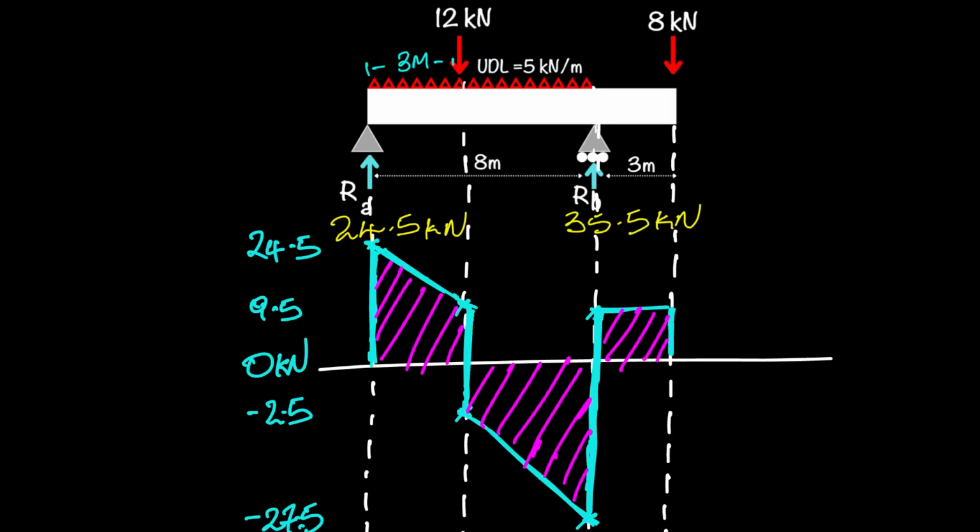So this now is the shear force diagram that we would expect to plot, and I'll just talk you through the coordinates so you can see that it's the same values that we have used before. So right here, starting from that point, that's our 0, 0 point right there, which is basically our starting point, and you can see now where that goes up all the way to that 24.5 kilonewtons. And then at this next point right here, that's us coming back down at the 3 meter.